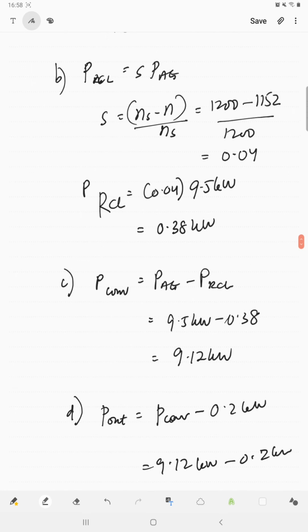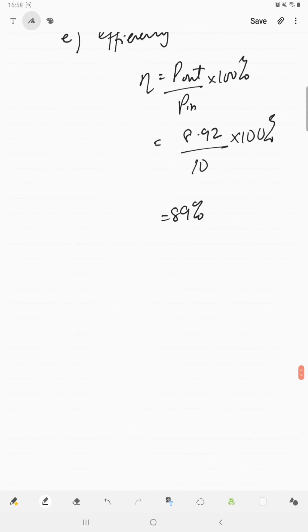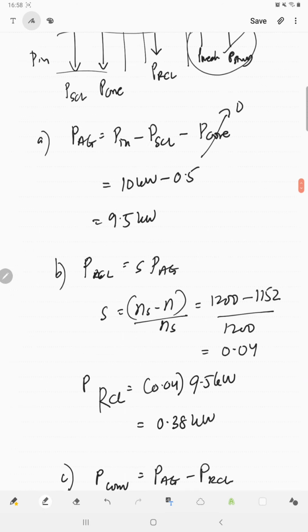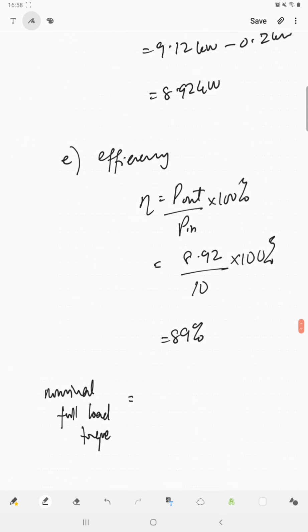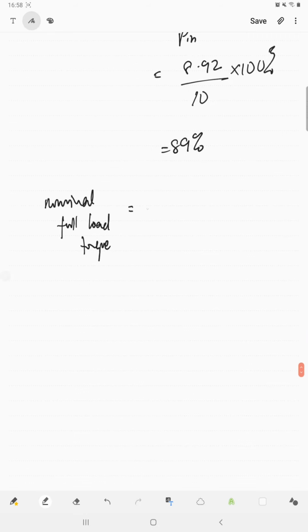If you look at the lecture notes, we have to consider the amount of air gap power. So it's 9.55 times P air gap divided by the synchronous speed, which is 1200. So this is 75.6 Newton meter.